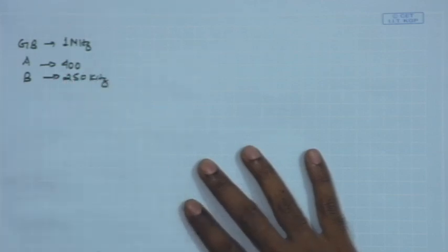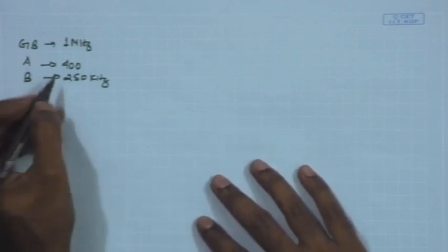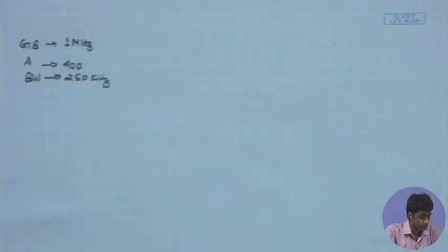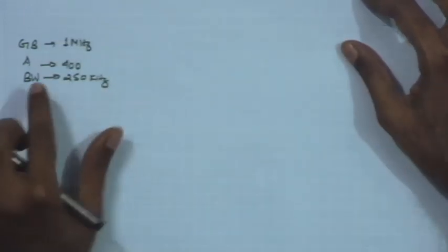So, these are the values we estimated, and based on these we need to look into the design of the comparator and specify, first of all, the sizing depending upon the gain and bandwidth values. Also, one of the targets would be to minimize the bias current, because ultimately it is an area constraint and power constraint design, where we are supposed to minimize area of the single channel acquiring the biopotential, and along with that we are also supposed to minimize the overall bias current in different analog units.